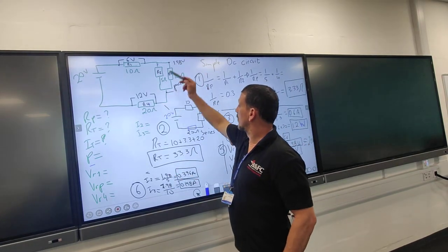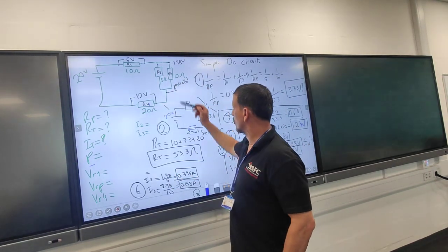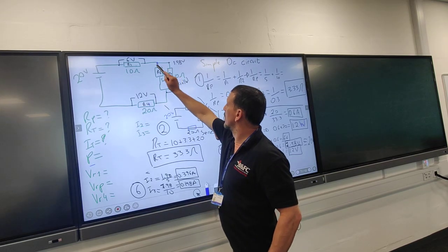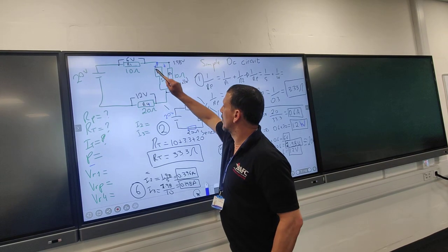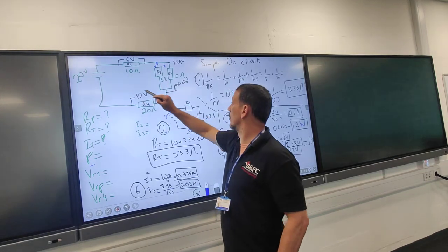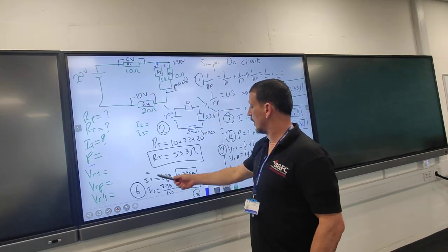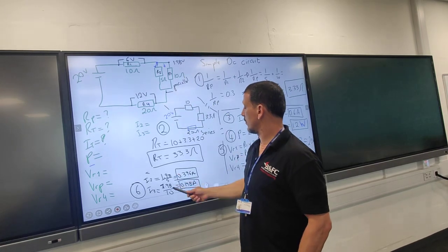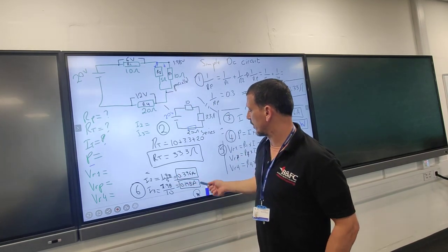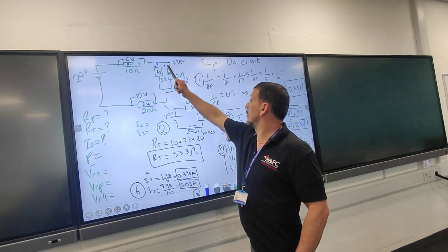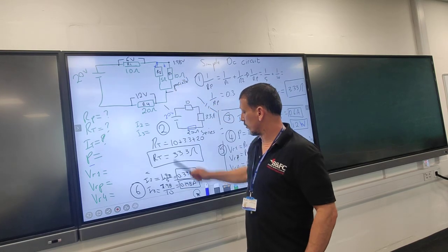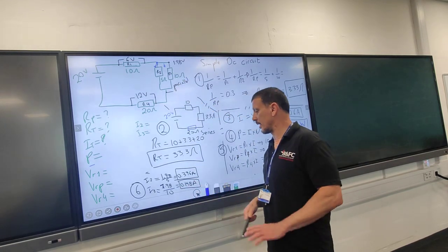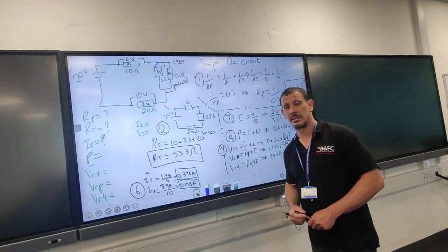And finally, I can find out what current goes through R2 and R3 simply by working out the voltage divided by the resistances. So we know that the current, when it gets to this branch, splits into I1 and I2. The current that flows around the system is I, its total current, but in this branch it splits. So I2 for resistance 2 is going to be the voltage divided by 5, which is 0.39 amps. And for I3, the same voltage divided by 10 ohms, which is going to be 0.19 amps. That's the end of this question, okay?